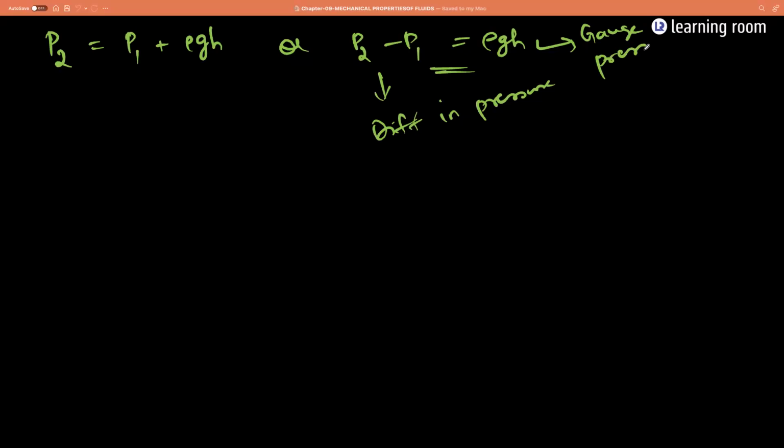That pressure is the excess pressure, and this is the absolute value. Why did I say it's an absolute value? Because it is telling you the pressure at the exact point. So pressure at the exact point is equal to pressure at the topmost point plus density of the liquid into acceleration due to gravity multiplied with depth. Not height, depth.